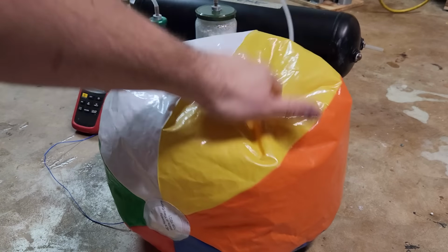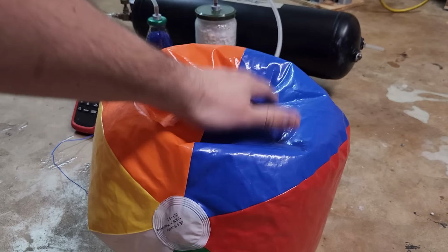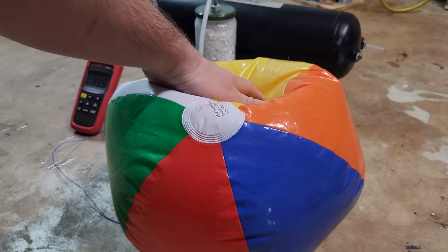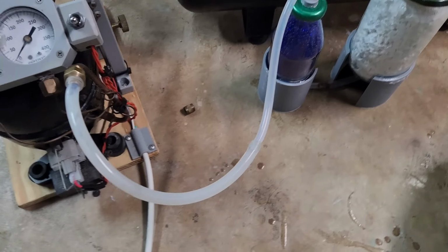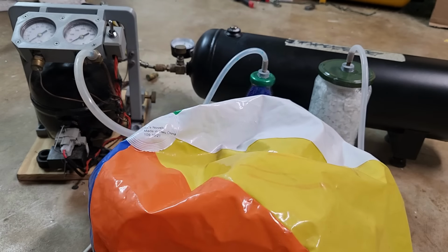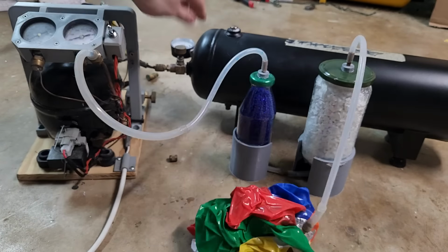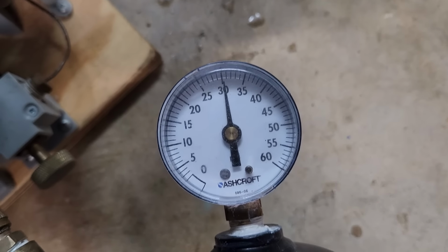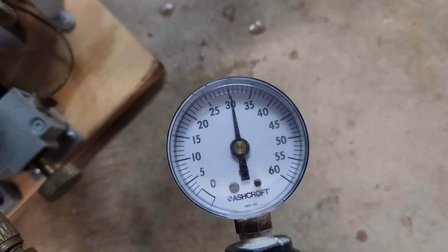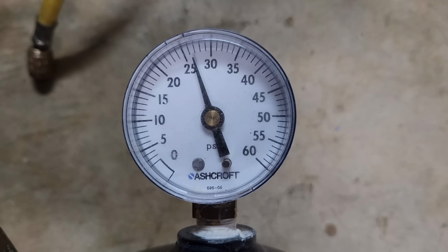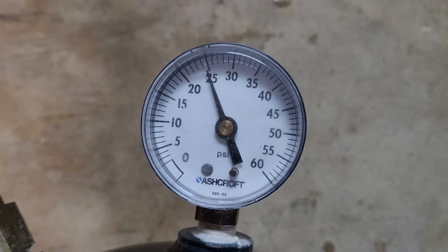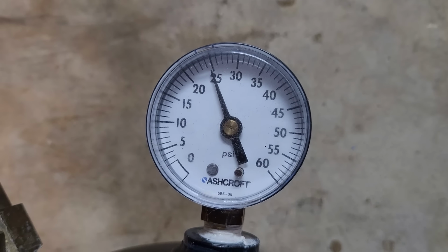The beach ball was only partially filled after the first scrubber run, probably around 20 liters or so, whereas I had started with about 32, so I'll have to do a few more runs. I'll reverse the process by sucking the gases back into the tank through my refrigeration compressor, forcing them to travel through the scrubber once again. And after those 2 passes through the scrubber, the gas pressure in the tank is down to 30 psi from the original 50. Note that there weren't any leaks in the lines. After another 2 cycles, it's about 26 psi, and another 2 puts it between 24 and 25 psi, so I don't think there's much CO2 left to scrub out now.